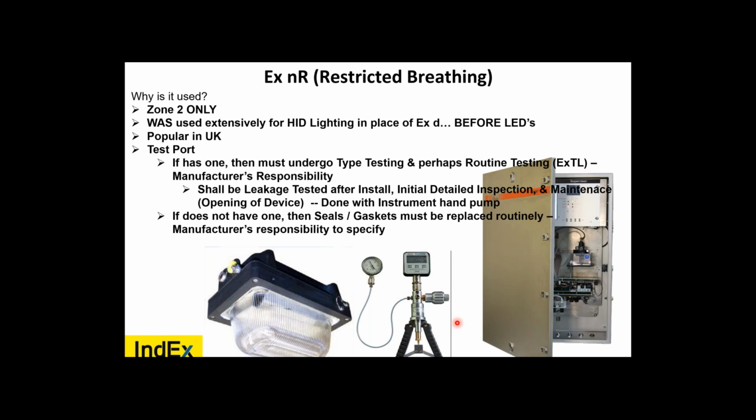Here's the problem with ATEX, manufacturer self-declaration. Now, if you involve an ATEX notified body like Ex NB or other ones, well, they know how to do the testing, or I should say, know which testing has to be done, who it can be sent to. Now, does it have to have a test port? Well, if it does have a test port, then it must undergo type testing and perhaps routine testing by an Ex TL test laboratory. And it's the manufacturer's responsibility.